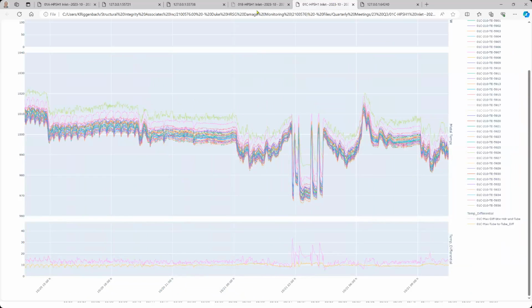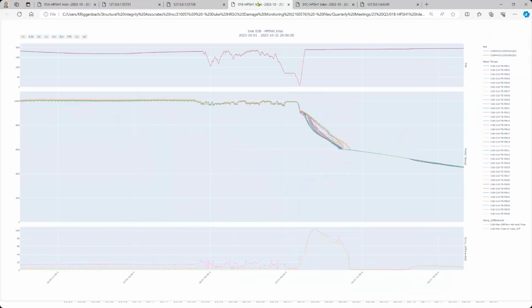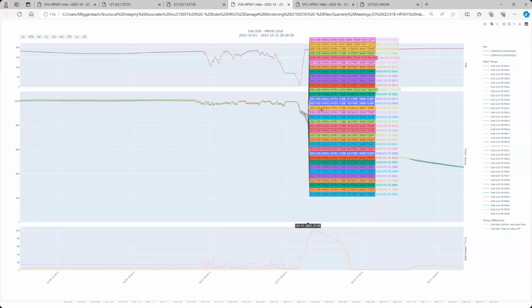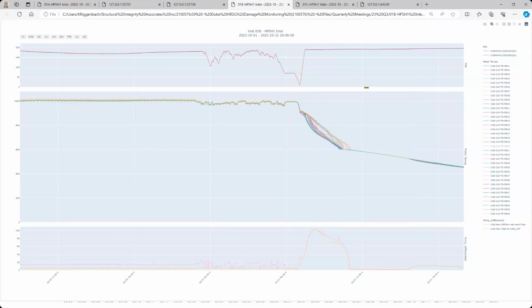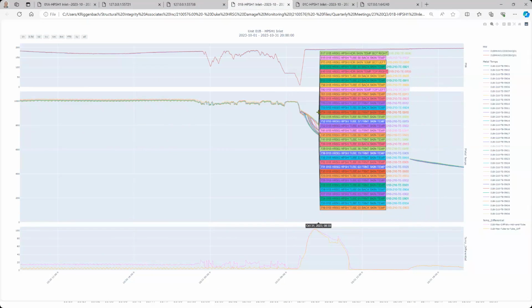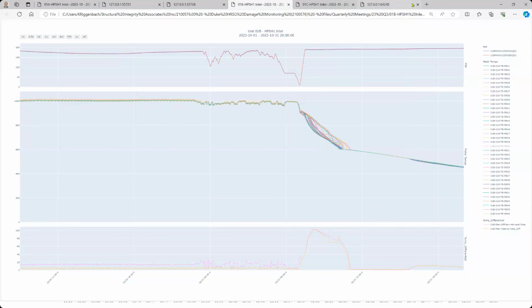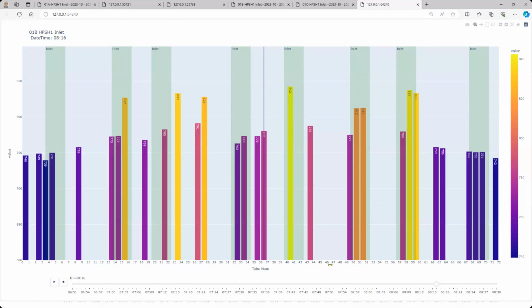The one other one that I just wanted to show real quick is a shutdown from the other unit, which also has similar differentials in those tubes. And if we plot this one up, you can see one of the things that looks like it's happening is the inlets are at different temperatures compared to the tubes away from the inlet areas.